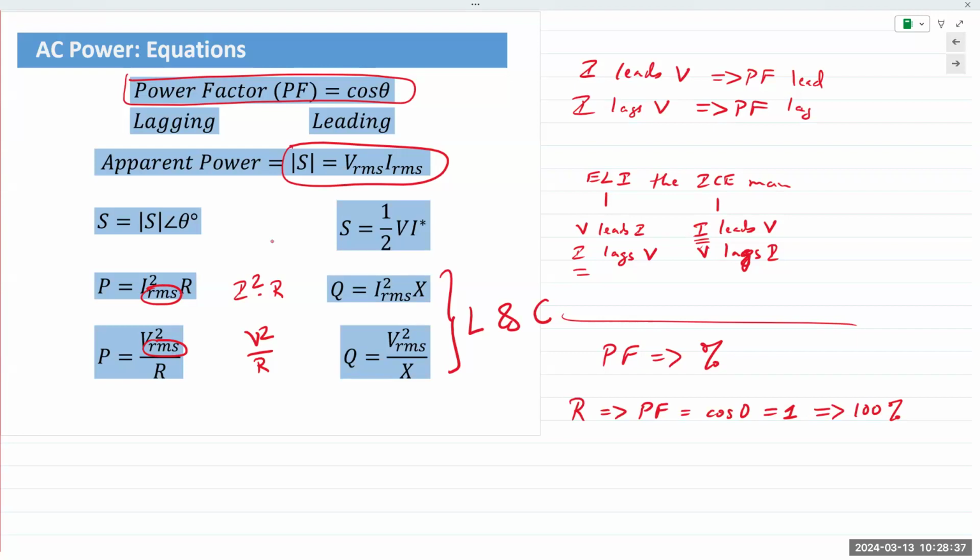As an example, let's say PG&E sets a limit of 85% for power factor, which would mean 0.85. If an industrial client drops below 85%, PG&E would say, hey, you need to bring your power factor above 85%. Otherwise, we will not supply electricity to you.